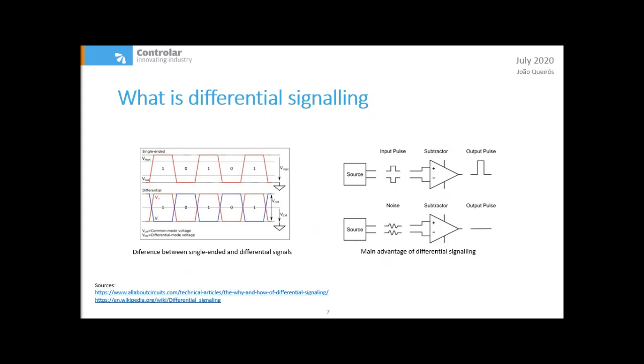By looking at this, we can see one of the challenges in manipulating differential signals. The data plus and data minus wires must be always together so that noise affects both in the same way. The main advantage of differential pairs is its immunity to noise. One big disadvantage, however, is the need of using two wires to transmit the same information.